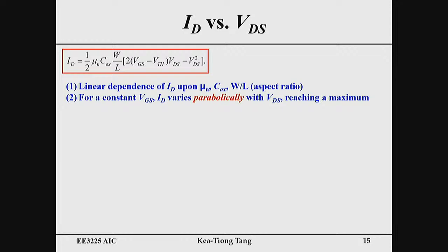The thing you will have control is W and L. Okay, one is channel width and another one is channel length. And just like what we mentioned yesterday, the current is proportional to W, inversely proportional to L, and inversely proportional to T oxide. Okay, so the formula said it well.